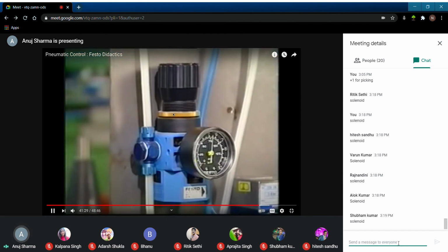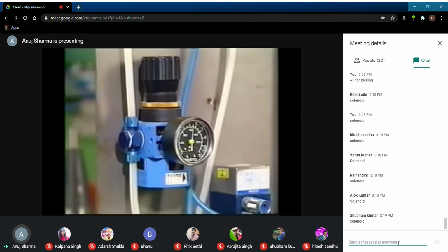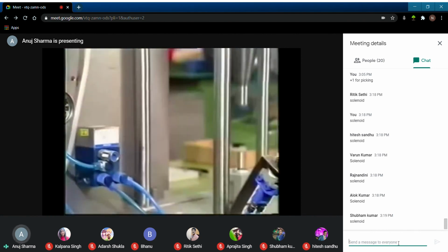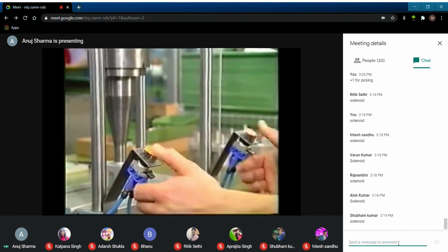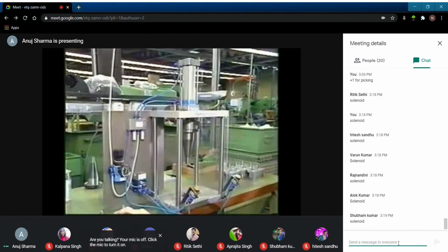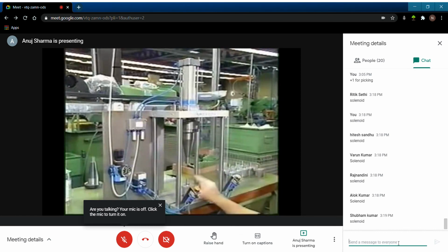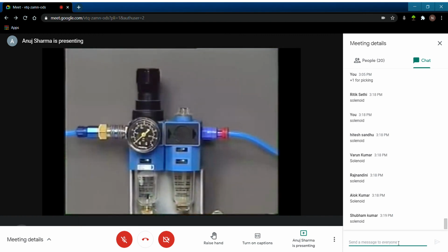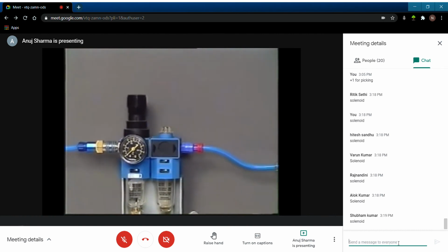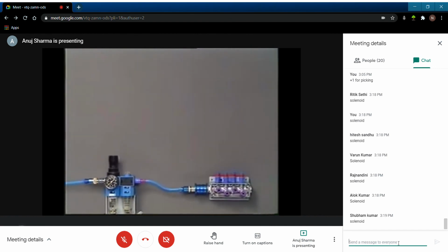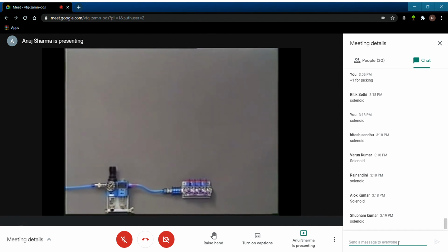Now that you are familiar with the individual components used in pneumatic circuits, let's examine how they form pneumatic control systems. The first component is the service unit. It's the link between the air distribution system and the pneumatic control circuit. Remember, it controls the pressure supplied to the circuit, cleans the air, and can add oil to lubricate the circuit